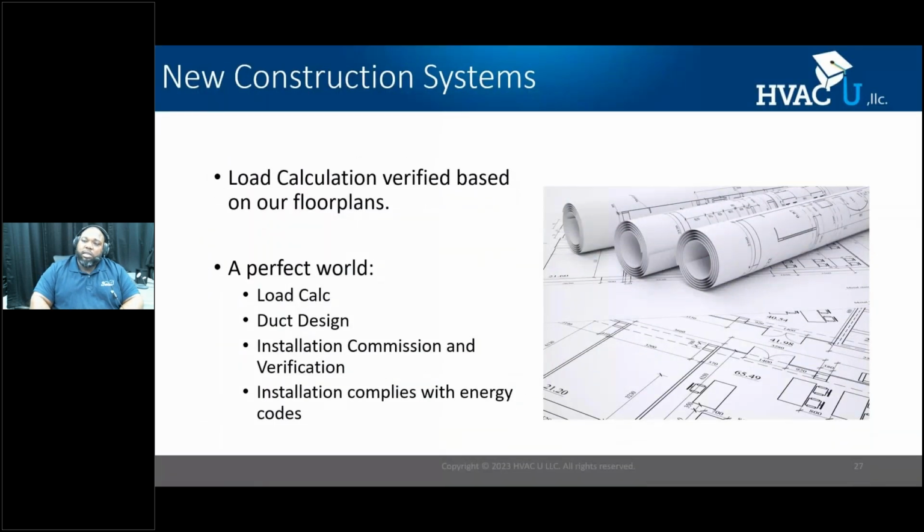So new construction, in a perfect world, you'll get a set of floor plans. You can do a load calc. You can do a duct design. The system is installed. It's commissioned. The commissioning verifies that the system design was correct. Everything works. The installation complies with the energy codes.